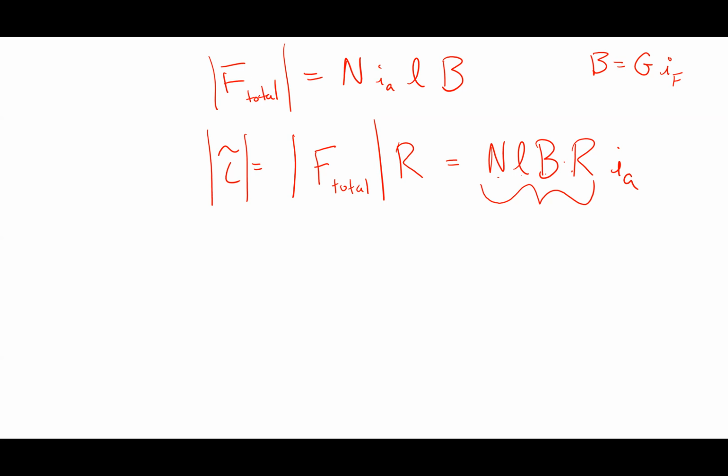Because I am basically saying, hey, I need more torque. I'm putting more mechanical load on this, just like if I had a pump, right? If I had a pump that I had to turn, it's got to push against the fluid. In this case, it's got to push against the friction of my fingers, right? And so it's increasing the current that it's putting out to try to produce that torque. All right. This guy does not sound like he's in good shape. But that's an important concept.